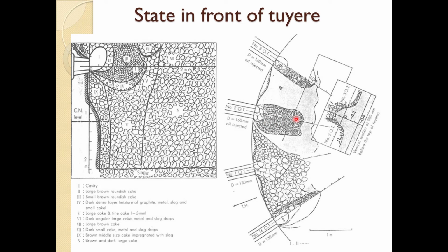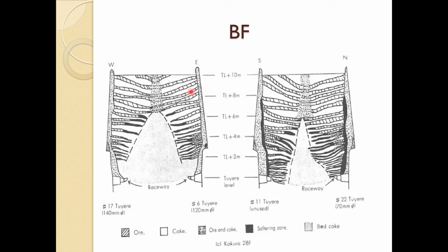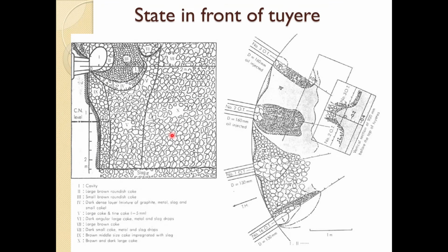So, this is a typical picture of the blast furnace raceway of the quenched one, and this is again, I would say, 4 decades old, and many things have changed. So, lots of attention is paid now to the coke quality, because you do not want lots of disintegration and generation of fines. Quite a bit of research has gone into this, and similarly into maintaining this structure, the raw material preparation and the coke preparation. These are very important for a smooth functioning of the blast furnace.